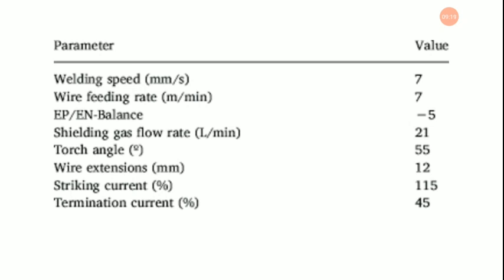The average values of penetration for each parameter at level 1, 2 and 3 for raw data are plotted. From the figure, it is very clear that peak current IP, frequency F, and pulse on time are the most significant process parameters compared to other process parameters. The figure shows that as peak current increases up to 200 ampere, the penetration value decreases, and penetration value increases with further increase in IP value.